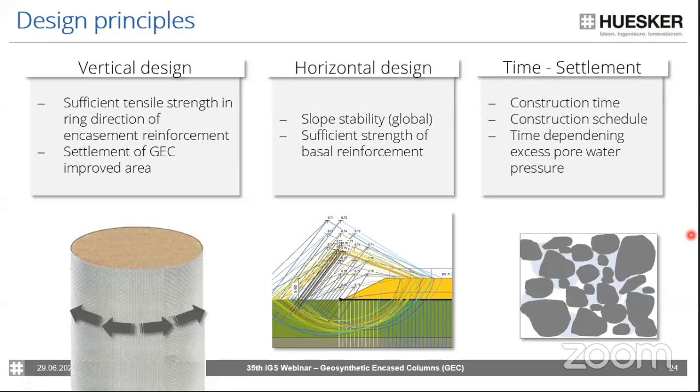Finally, you also do a time settlement analysis to analyze the construction time and also to help with the construction schedule. So very often the geosynthetic encased columns and the embankments on top are installed with filling periods and waiting periods, to wait for the excess pore water pressure to dissipate to ensure a safe construction. And then the next construction step follows when excess pore water pressure has dissipated.